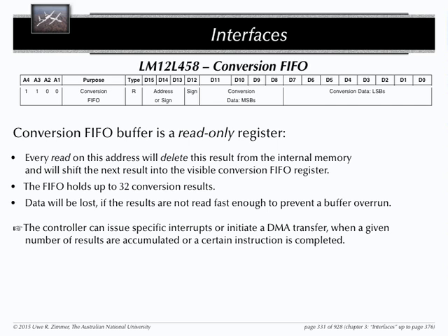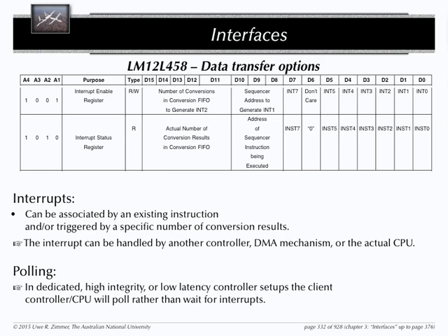So often these interrupt lines are not necessarily handled by your CPU, but only by DMA controllers, direct memory access controllers. Those are independent units which are only there to shuffle memory between devices and memory or between memory areas. Obviously, this thing can trigger a number of interrupts, and this is the interrupt status register, which you can use for that. Or you could use explicit polling if you have plenty of time at your hands, or you want to be extremely close to the actual conversion.